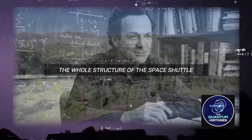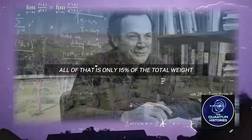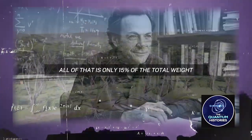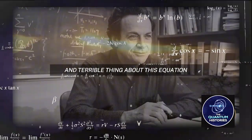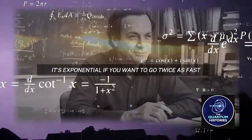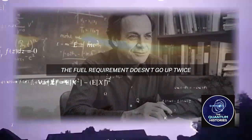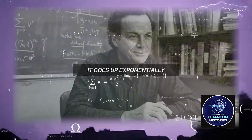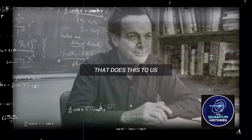The whole structure of the space shuttle, the engines, the payload bay, all of that is only 15% of the total weight. The rest is fuel. And here's the beautiful thing and terrible thing about this equation. It's exponential. If you want to go twice as fast, the fuel requirement doesn't go up twice. It goes up exponentially. It's that natural logarithm in the equation that does this to us.